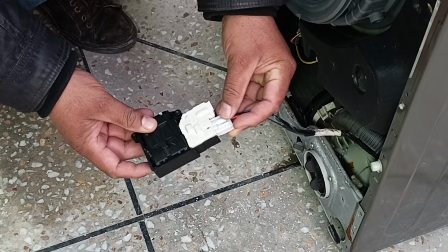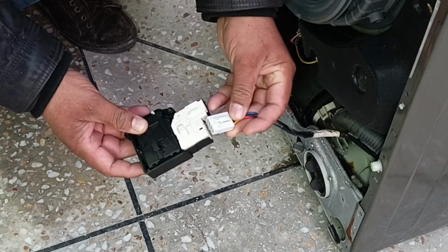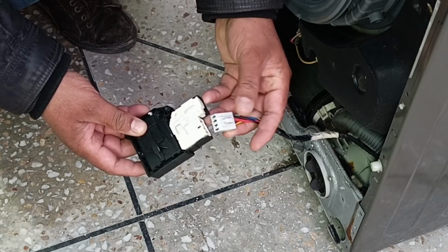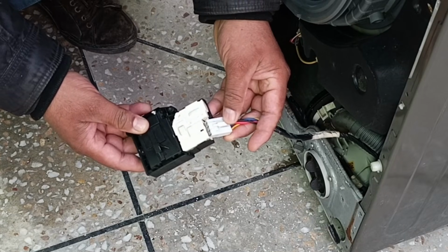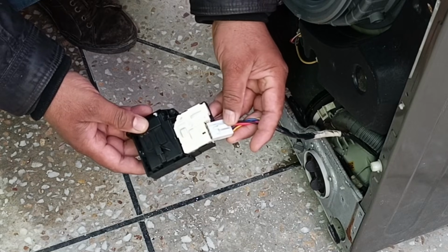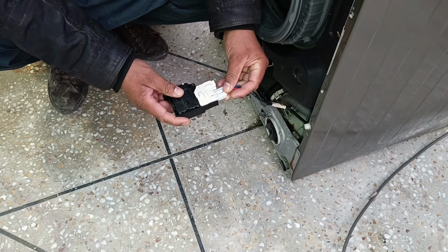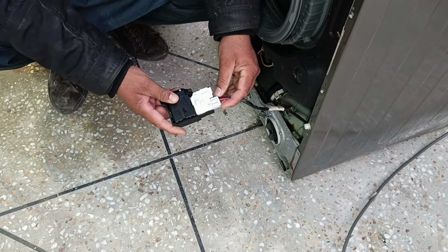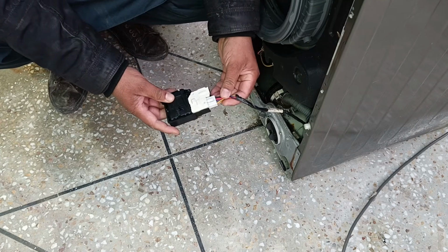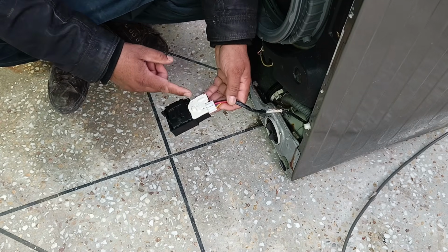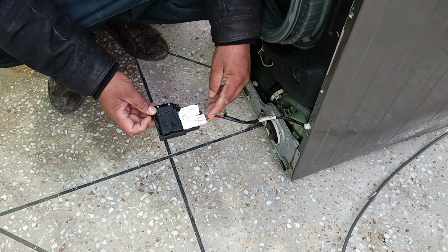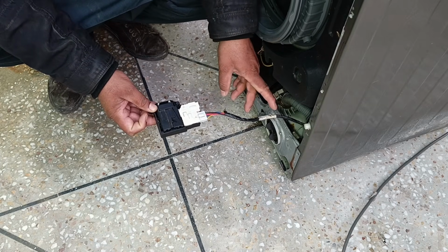Besides that, as you can see here, if the connector has a loose connection, that can also cause the problem. In that case, the machine will directly show the dE1 error. If the connector is properly fitted and there is no loose connection, then there may be a wiring issue, which can also lead to this problem. If everything else is fine, then the problem may be inside the PCB, and it will need to be checked.